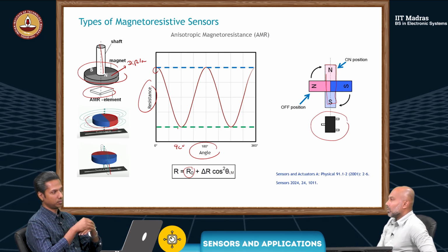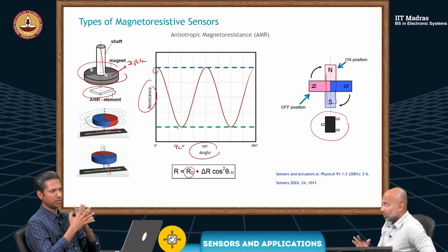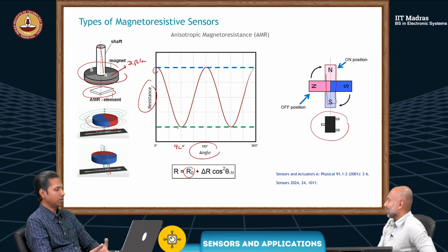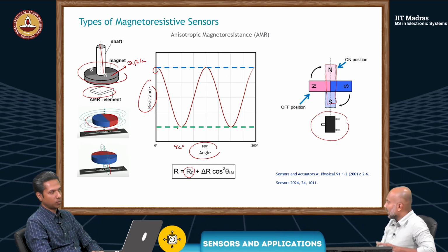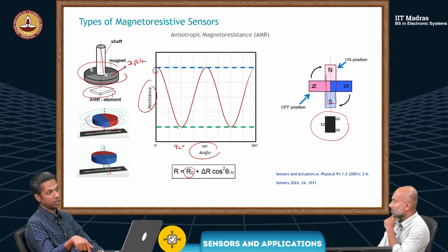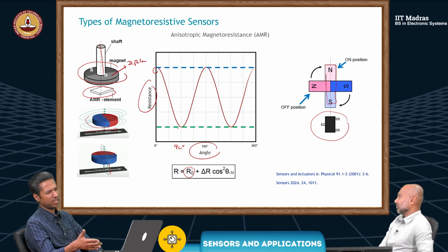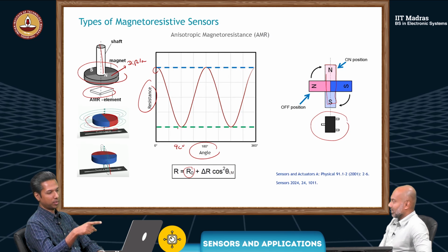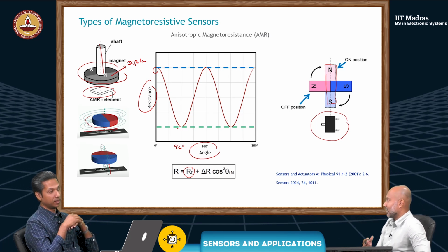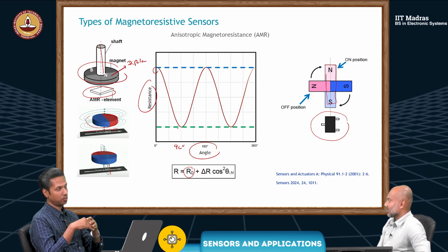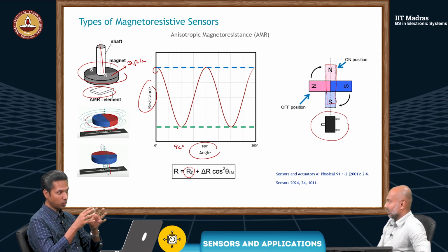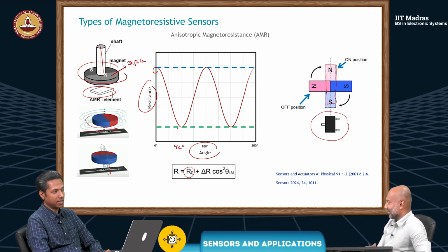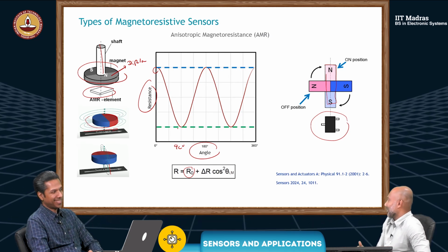When you say large, you're probably talking about kilo ohms. Yes, that's what I'm talking about. Not mega, but high. So maybe it's in that range. Because when we talked about the strain gauges, it was like 350 ohm, which is pretty small. It's in the ohm range, but this will be much higher than, let's say, 10 or 20 ohm. So the associated power loss will also be less for the measuring circuit, because remember, you also have to give a current to the material, right? It just doesn't change its resistance based on the current. Correct.